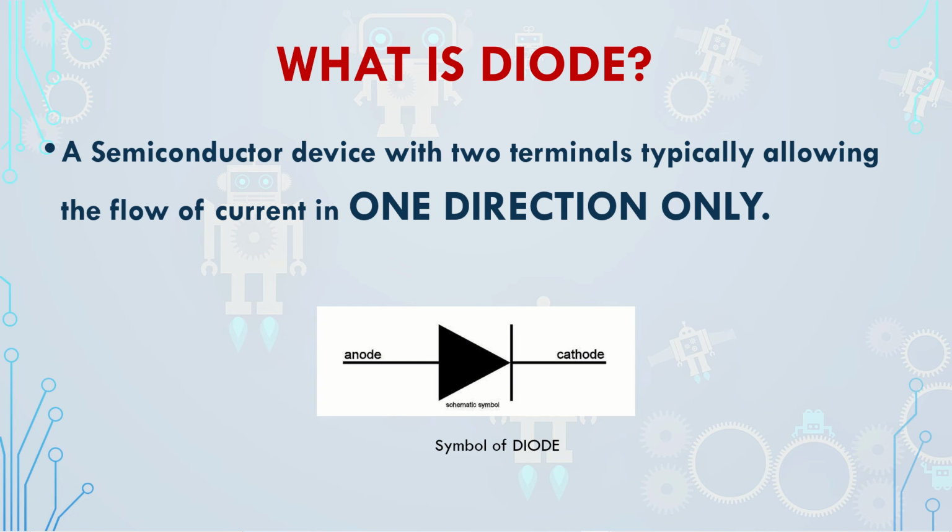What is the meaning of that? One terminal is called the anode and the second terminal is called the cathode. This is positive, this is negative. I have to identify that also. We discussed yesterday in the Tinkercad software that for the LED, the leg which is very straight is the cathode, and the one which has some angle is the anode. So the anode acts as positive, and the cathode acts as negative.